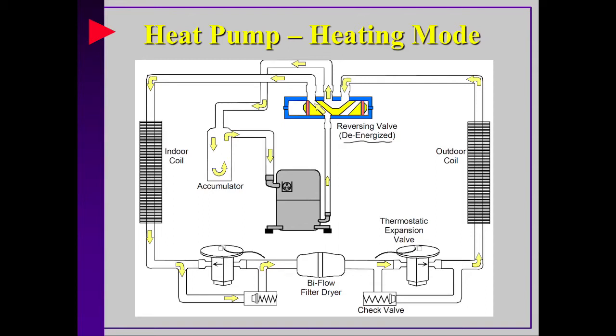Now, of course, there's going to be, let's call it, the inside TXV or an inside metering device. But in this case, we're showing a TXV, and this one here is the check valve. Most all modern TXVs that are used for heat pumps, this check valve is actually going to be built into this device as an integral part. For the sake of doing this image, it's easier to show it as a separate part. But in real life, most of these are going to be built into the TXVs.